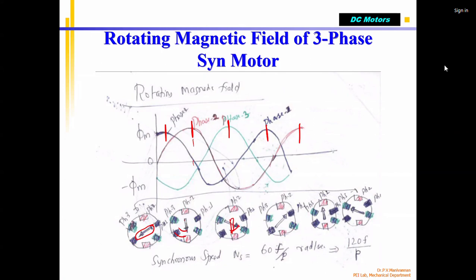So you can see that it originally rotated this much, rotated this much, rotated. After 3 peakings, the rotor, which was like this, has come to a new position. Correct? So it was something like this. For understanding purposes, we can say that it was like this. Now it has rotated this many degrees, and this many degrees, through all 3 phases. Again, you can see that the blue phase is peaking. Correct? From blue, again the rotor from here is moved this many degrees. Next, again the red phase.